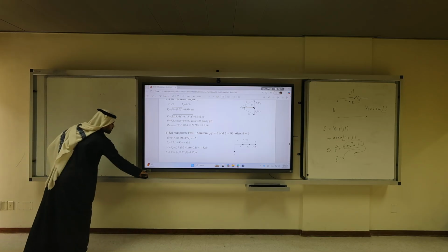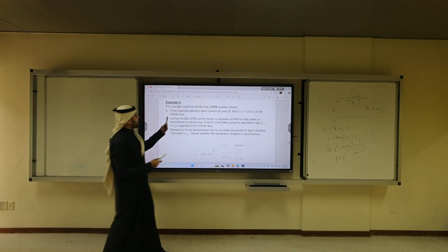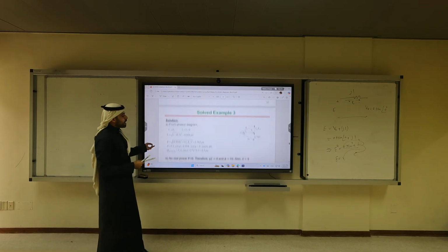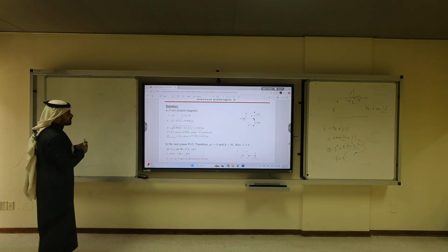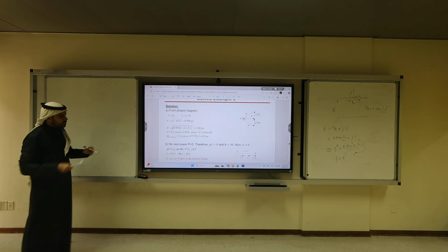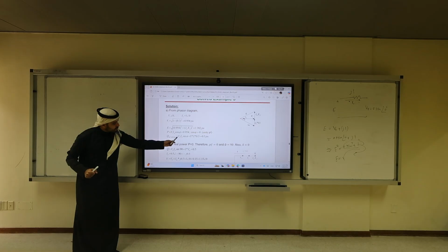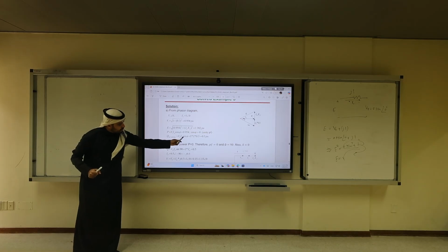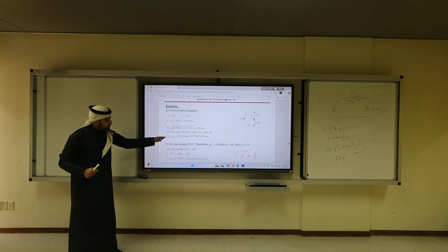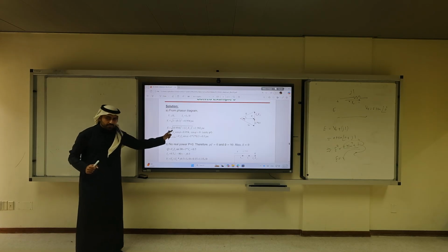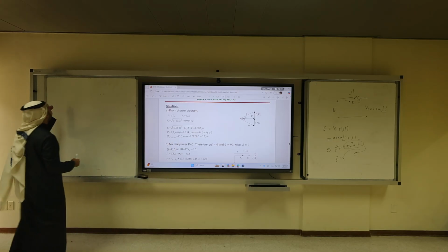To get the real power, where are we measuring the real power? At the infinite bus. So we have to measure it using... here's the thing. Why here he used VtIa cosine alpha, here he used VbIb sine alpha. If you measure it at the infinite bus, for Q you have to get Vb of the infinite bus and Ib of the infinite bus. So let's go back to the original equation.